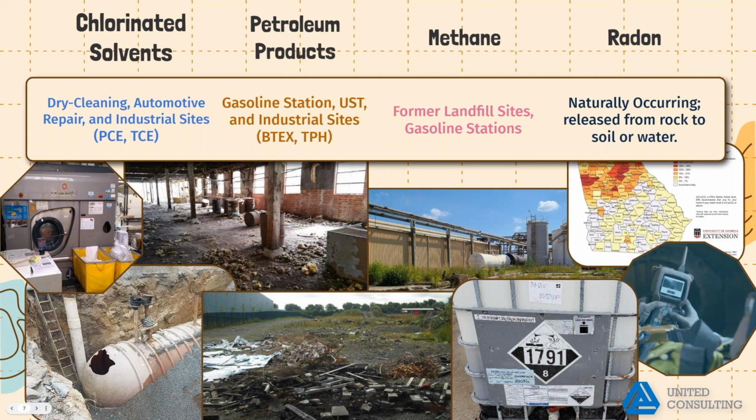It definitely raises the bar, if you will, for selecting the correct mitigation strategy and understanding the contaminant you are dealing with. In a sense, beyond radon, methane has a significant contribution to the beginnings of vapor intrusion and was a precursor to where VI has come today. As many petroleum compounds rapidly degrade over time, they will end up off-gassing methane or other constituents that will degrade into other daughter products. These lead to evaluations for mitigation down a long-term exposure pathway.